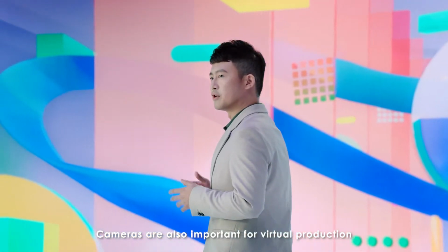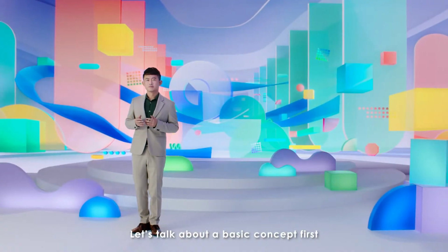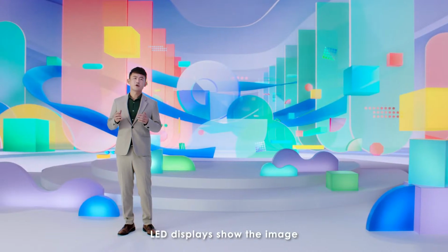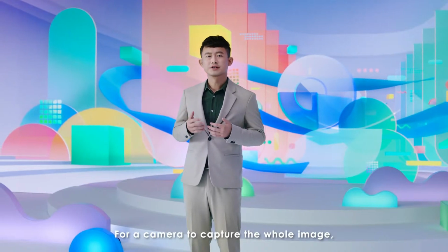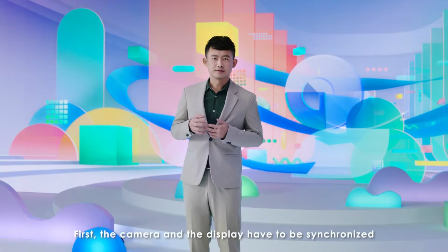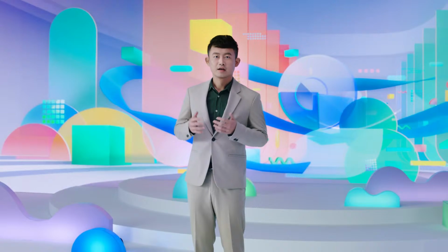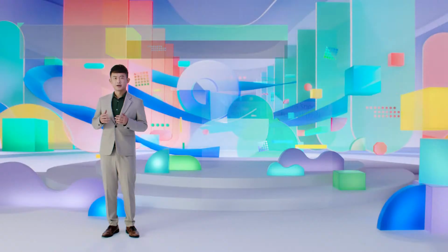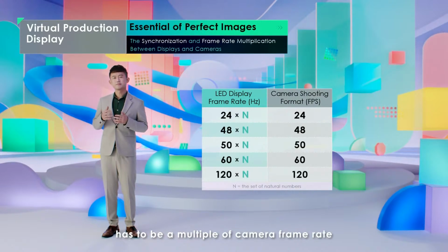Cameras are also important for virtual production. Let's talk about a basic concept first. LED displays show the image. For a camera to capture the whole image, there are two things to consider. First, the camera and the display have to be synchronized. This can be achieved with the controller's Genlock function. Second, the frame rate of the display has to be a multiple of camera frame rate.